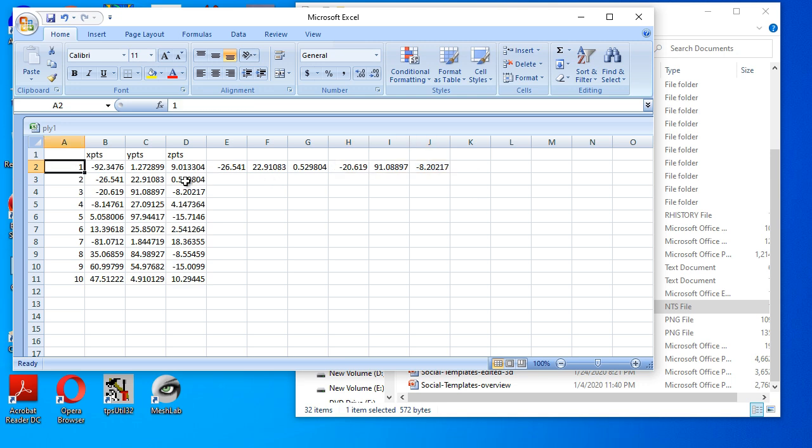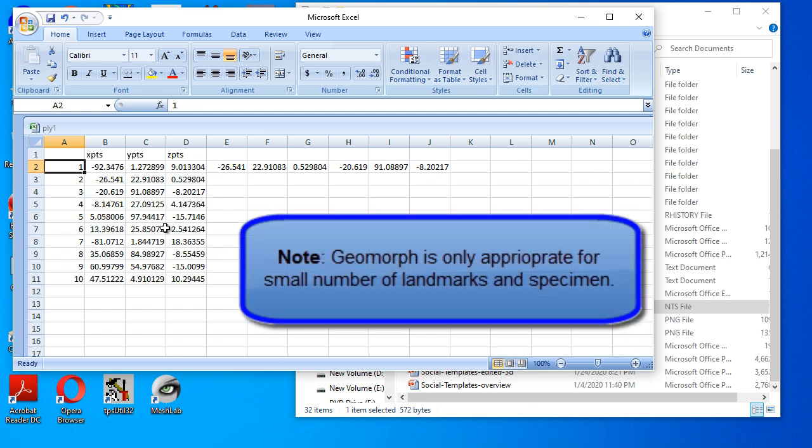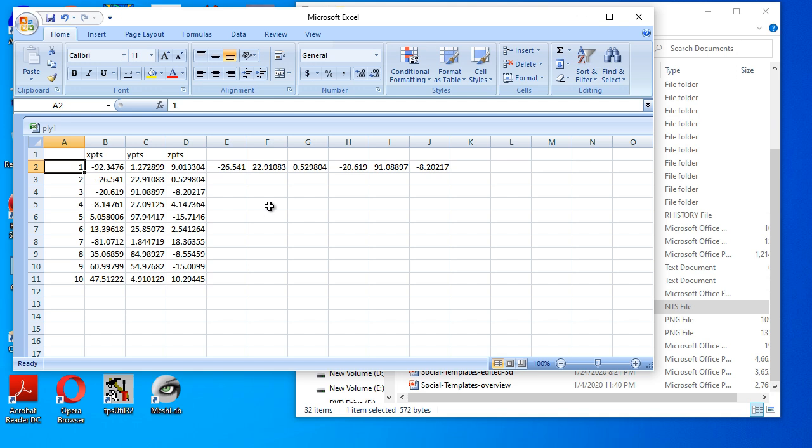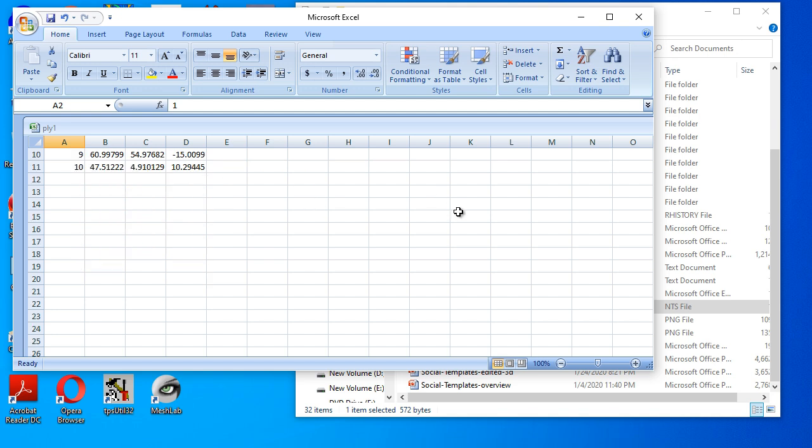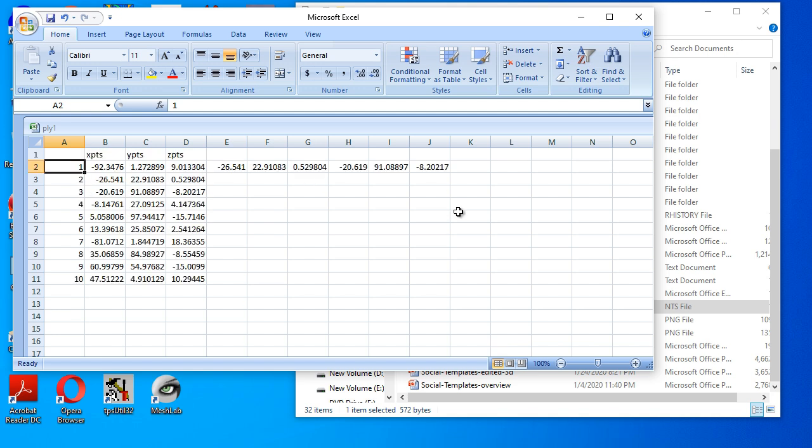Then for specimen 2, we do the same thing, and put them on a straight line. If you have a lot of specimens, you may not want to be copying and pasting. You may want to use something like Python to write a short program to automatically generate and align them. Maybe we may look into that next time, not under this course.